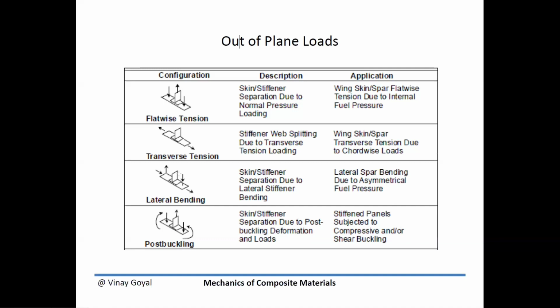Post-buckling is another situation you could have. It could be due to a combination of compression loading. Even lateral loads can cause buckling. And so stiffened panels subject to compression loading is an example where you could see this.